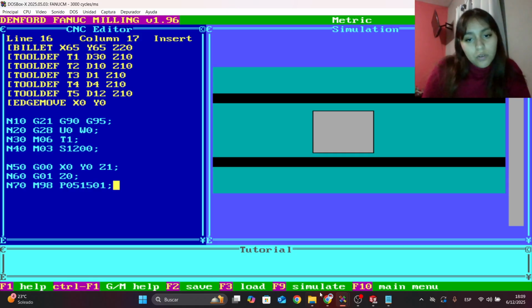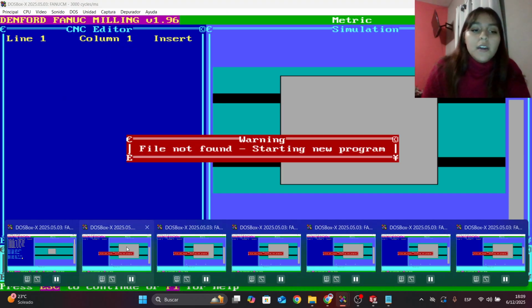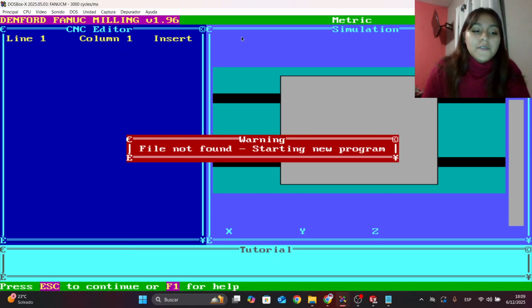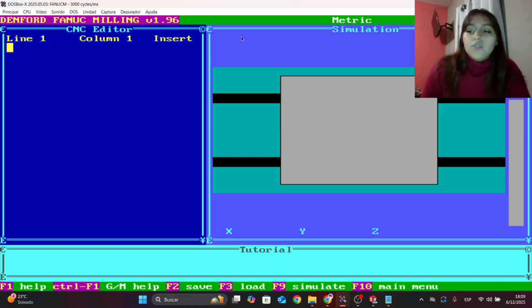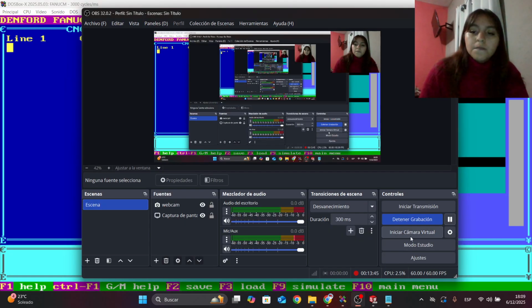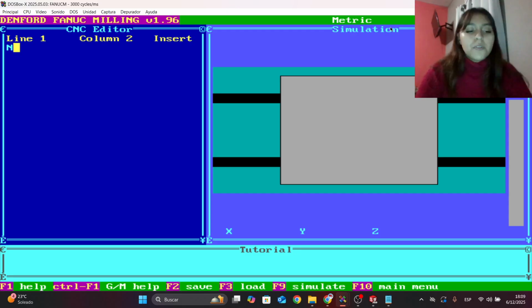Now we have to open another program. I have all of the subprograms here. So in this subprogram, we can start doing our piece. A second. Now for the subprogram, we start again with the count of the lines, and now G91, that was the incremental system.